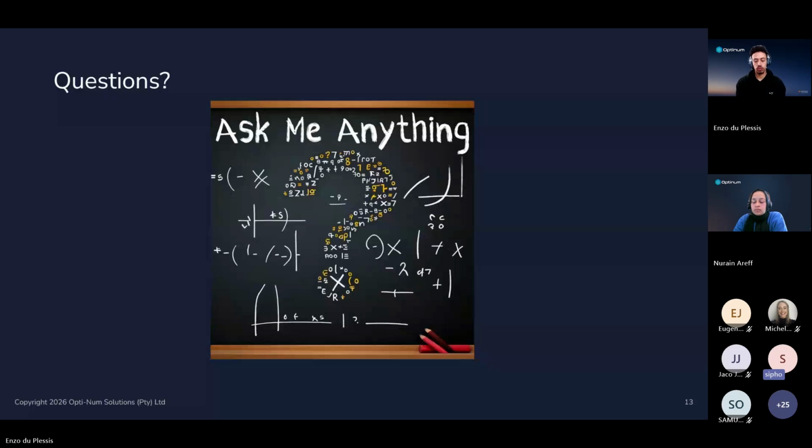But now the problem, I'm modeling first, right? The problem I'm experiencing is that I've completed the model, but when I wanted to do a load flow analysis on it, I just keep getting errors. I am correcting the errors, but on one of the buses I'm getting a 0 voltage, and I think that bus is making my whole model not respond well on the load flow. So I've corrected the parameters.